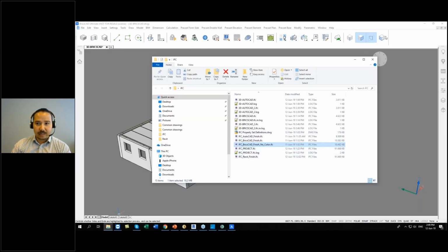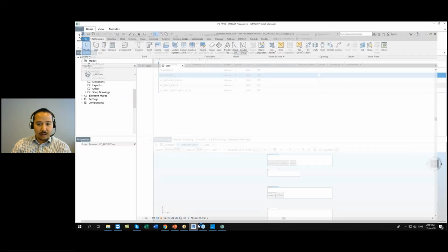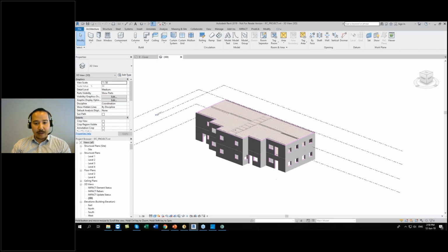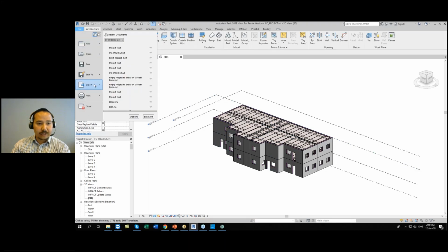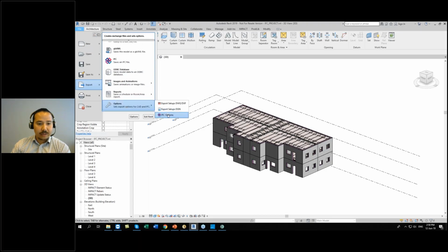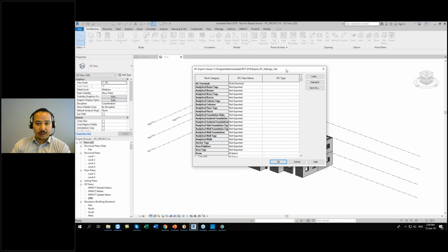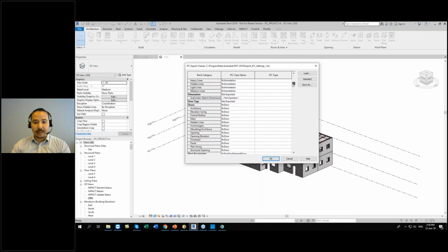So last but not least, let's take a look at Revit. In here in Revit, I have my model also. And as I told, there are a bit more possibilities in Revit for the export. If we go up to File, Export, instead of choosing IFC, we go down here to Options and choose IFC options. In here, we get the Revit category, we get the IFC class name, and we get a long list.